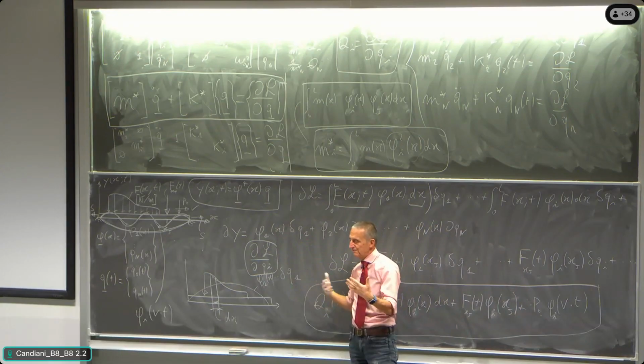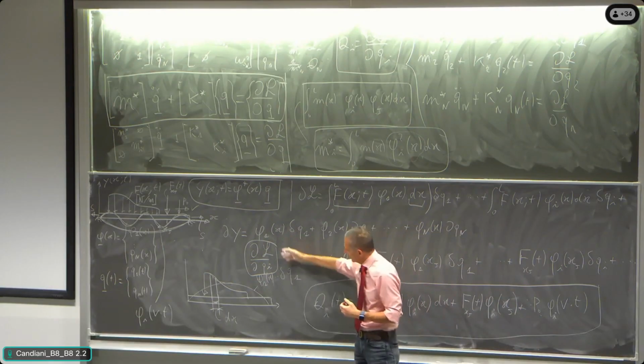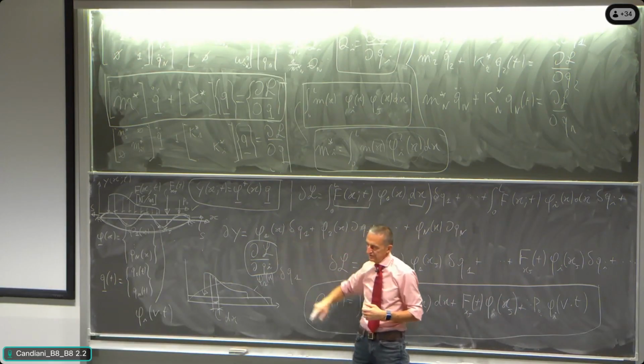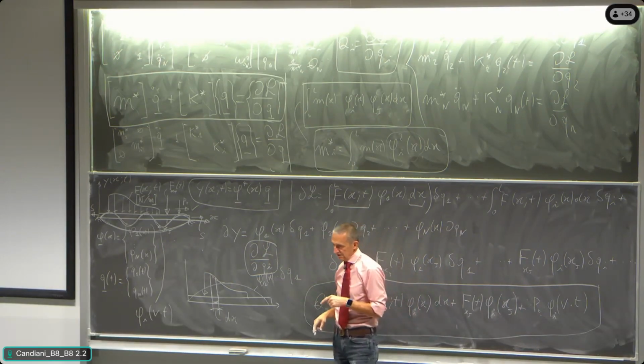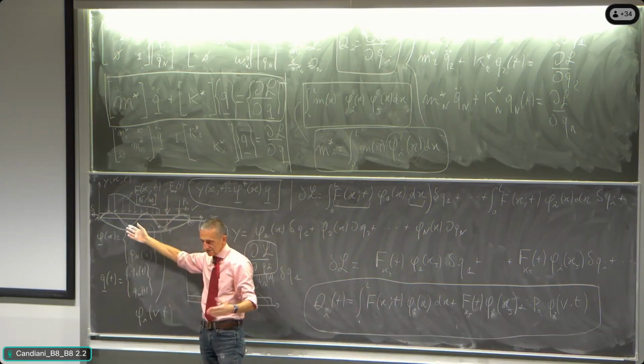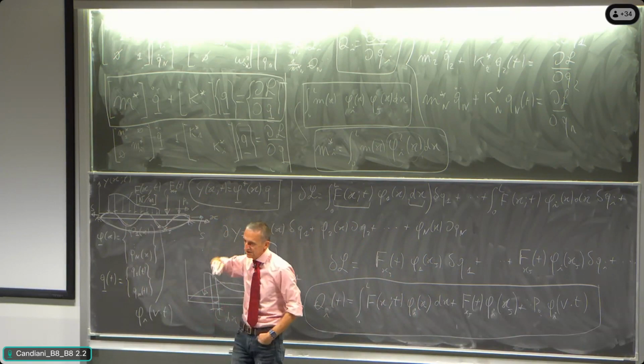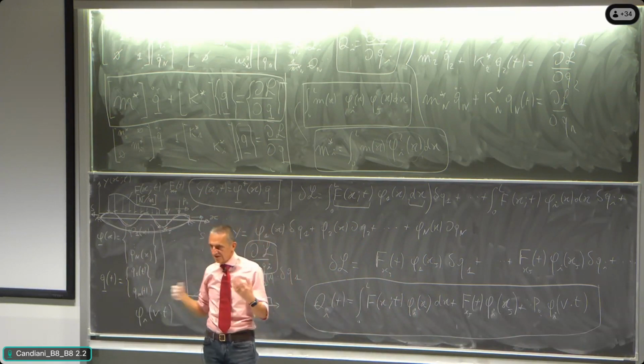So there is a perfect analogy for what we do in the vector fields of forces, and the meaning of this operation, taking the partial derivative with respect to the qi coordinate of the virtual work, is exactly the projection of the very complex system of forces over this versor that is the modal shape. There is an analogy.